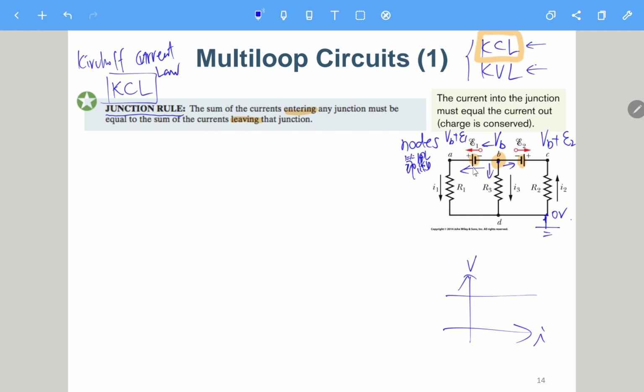So actually this I1 goes to here. So this is a resistor, so we may be able to find the current using Ohm's law. For this I1, I will not use this I2. I will just define I2 in the opposite direction, which means that we should have I1 plus I2 plus I3 equal to 0.